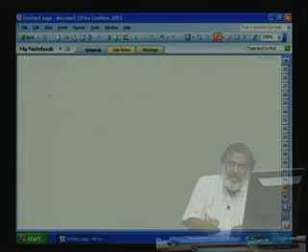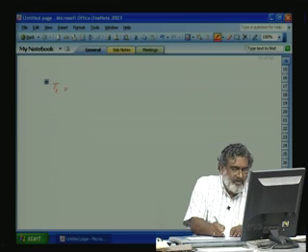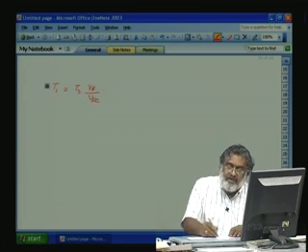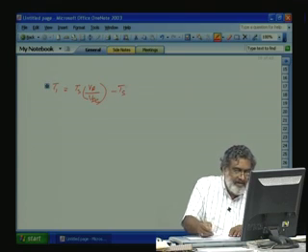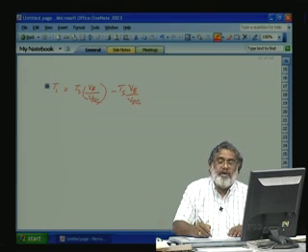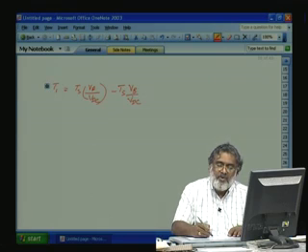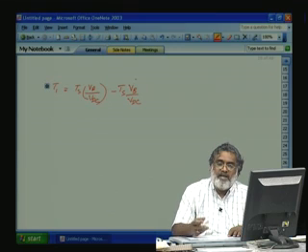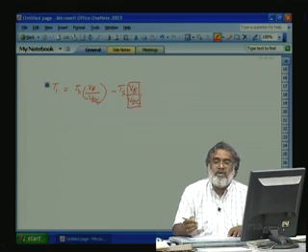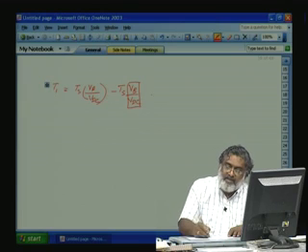See here, now we can write T1 is equal to Ts into Va by Vdc minus Ts into Vb by Vdc. Vdc is in volts, Vb is also in volts. So, for the maximum DC link voltage, what is the instantaneous sampled Va, Vb, Vc? So, this becomes a fraction, it is a constant. So, this can be represented as Tas minus Tbs.